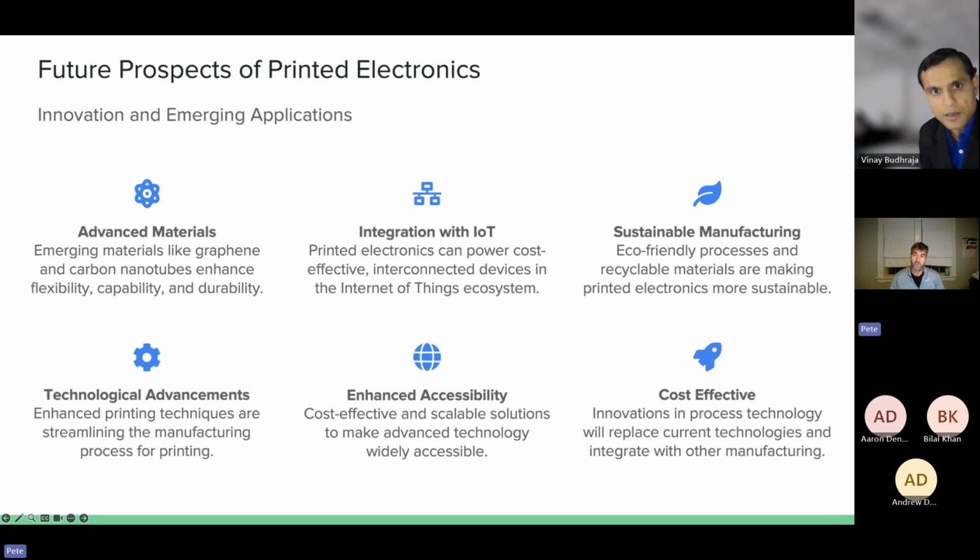The other advantage we found, and there's been a paper published on this, is when printing carbon nanotubes, one of the benefits of aligning them is the electrical capability. If you can have all the nanotubes aligned together, it creates a much better electrical conductor, a very highly conductive material. We found that by printing ours and drawing them out, it's actually aligning them quite a bit. There's been a lot of research in that area for the carbon nanotubes. So these are a couple of the advantages.